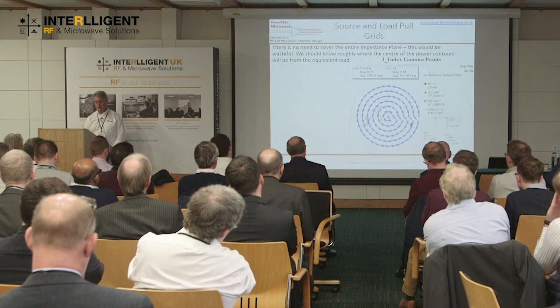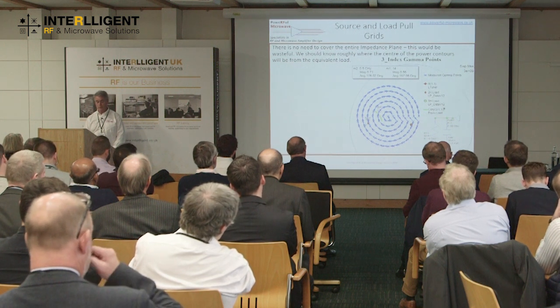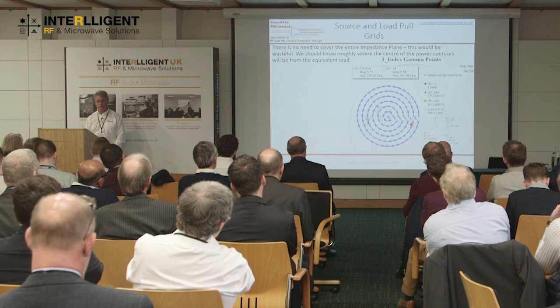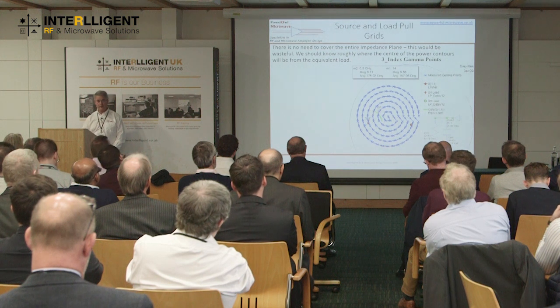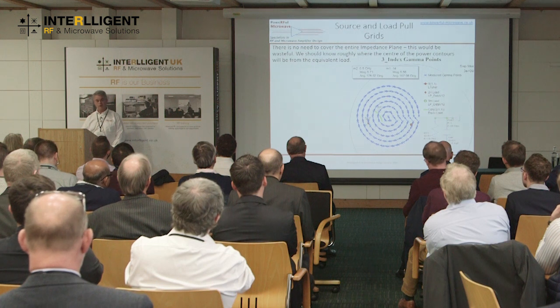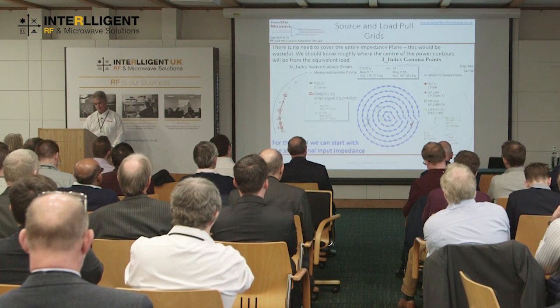Oh, and also at the moment, we've set our second and third harmonic impedances. I've plotted those as well. We've just set those to 50 ohms for these simulations. So they're quite important to bear in mind for the future, that all the measurements that we're doing initially are with our harmonics terminated in a 50 ohm impedance.